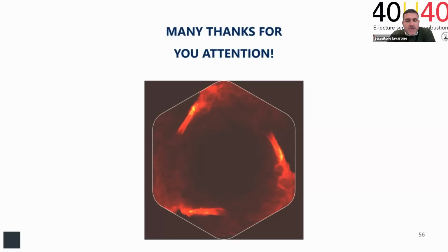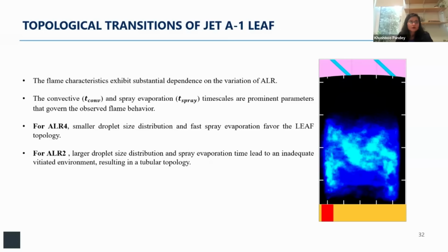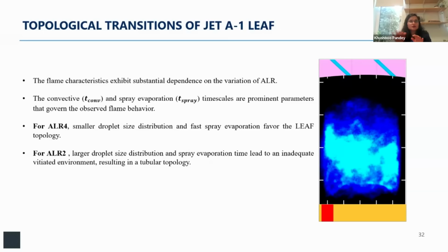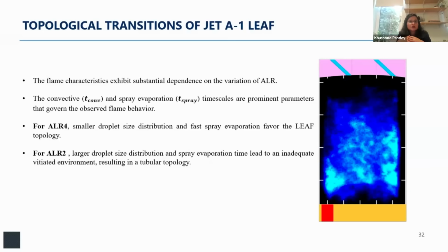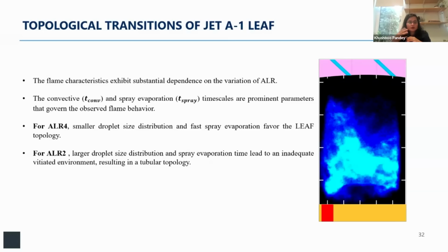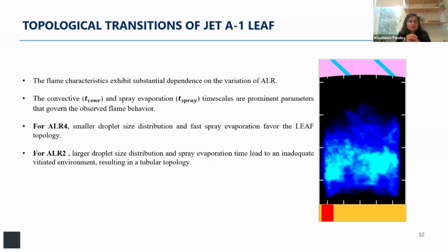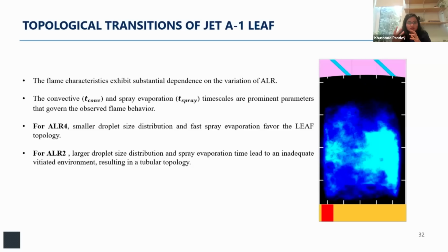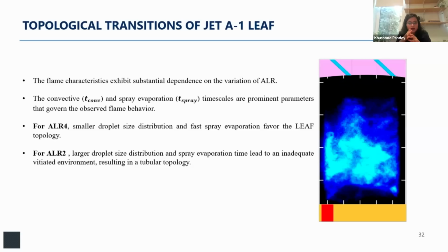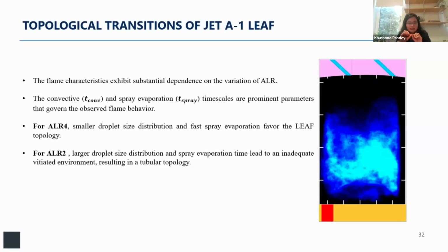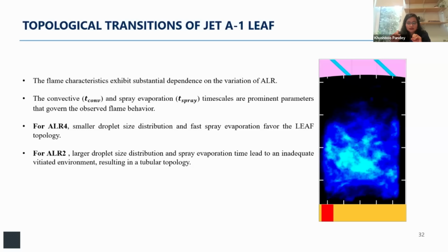Okay, I have a question regarding the flame structure when you talked about the hydrogen flame. What are the flame structures that you see in the kerosene spray? Okay, so for the spray in cross flow, if we do the PLIF of individual sprays, we do see that when we have ALR2, which means when there are larger droplet sizes, we see very thick reaction fronts, which is very diffusion dominated. But when we go at higher ALRs, that is ALR6, we start seeing these thin reaction fronts.